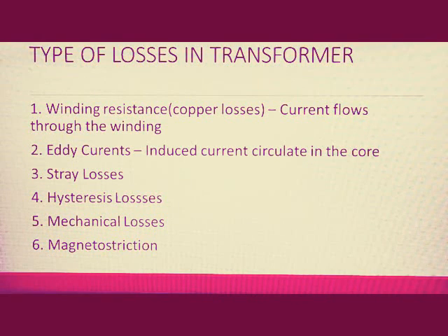Hysteresis losses: each time the magnetic field is reversed, a small amount of energy is lost to hysteresis in the magnetic core. The level of hysteresis is affected by the core material. Mechanical losses: the alternating magnetic field causes fluctuating electromagnetic force between the coil of wire, the core, and any nearby metalwork, causing vibration and noise which consume power.